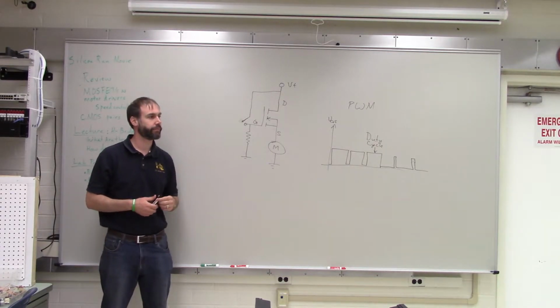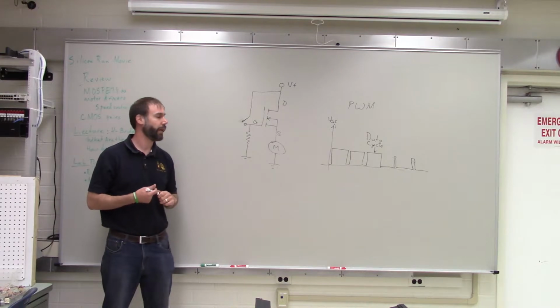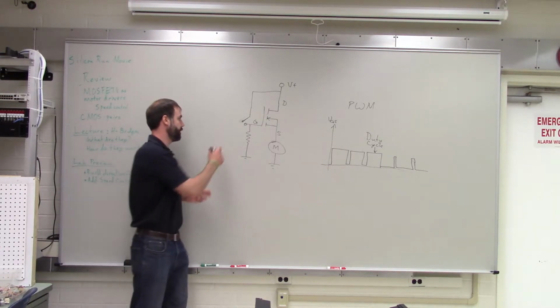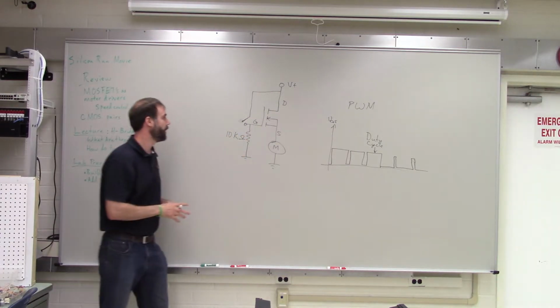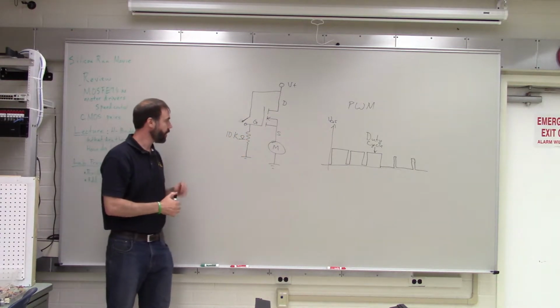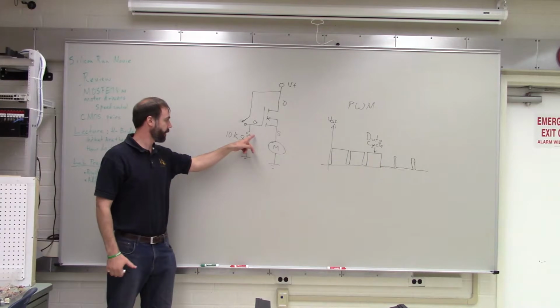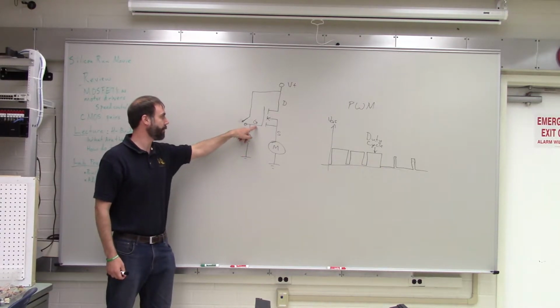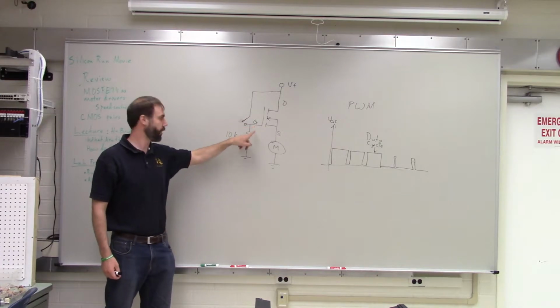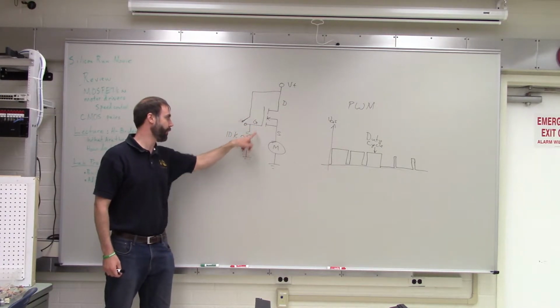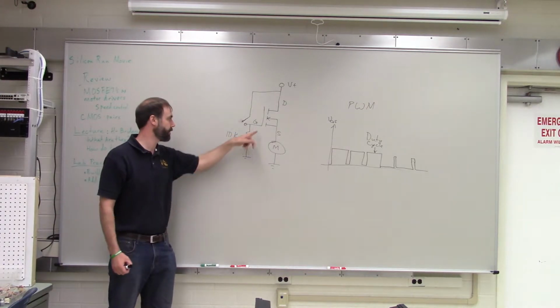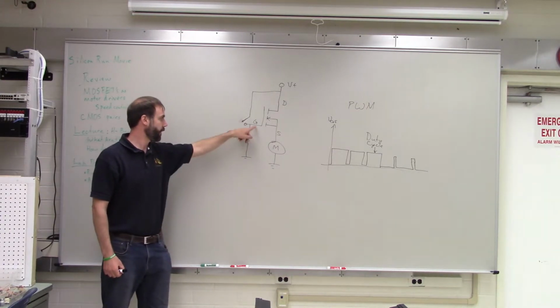Yeah. Is a resistor like a high value or a low value? High value generally. It's usually around 10 kilo ohms, give or take. It doesn't have to be very small because the amount of charge left on there is very little. So even a high resistance is enough to drain off what little charge is there. It just has to allow that charge to go down.